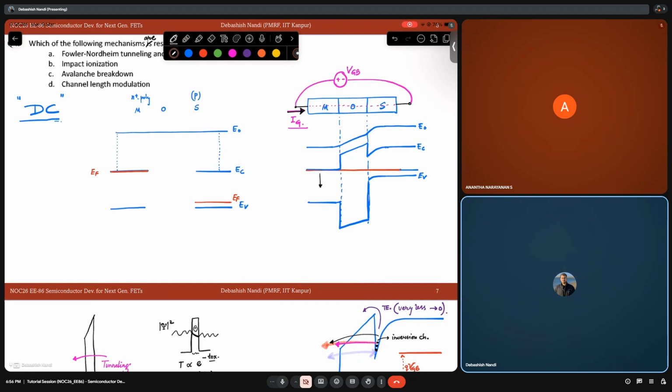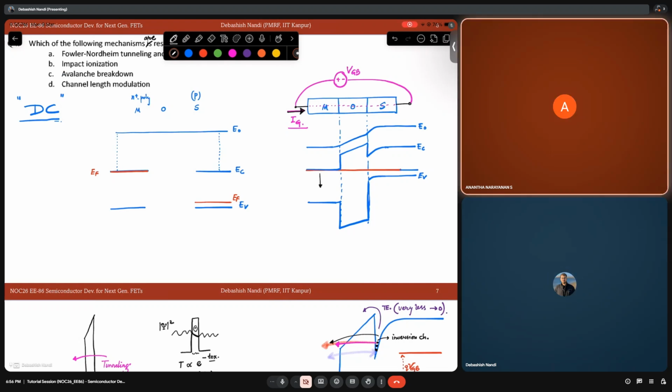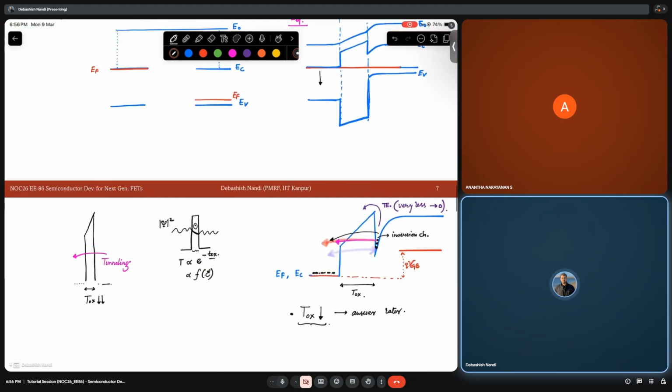Why? Because if the potential across something controls the current across it, I am losing my field effect, capacitive action, and it is becoming a resistor, which I do not want. I want a transistor action: high impedance at one node, low impedance at the other node.